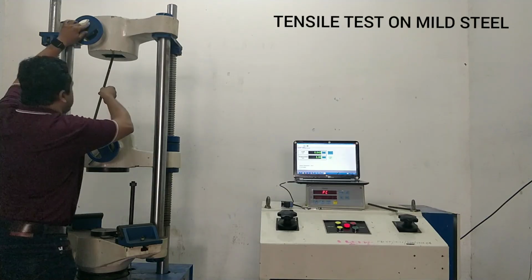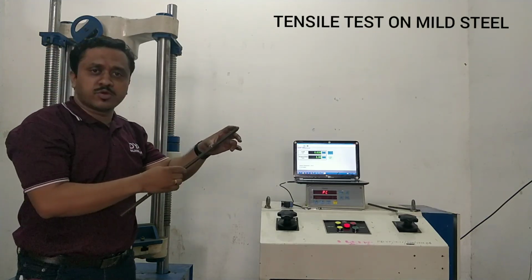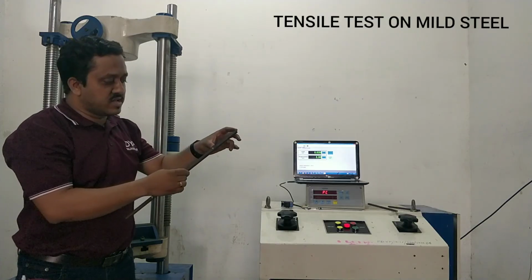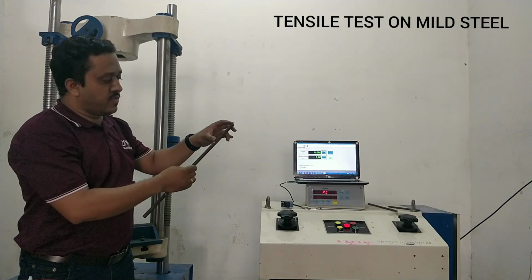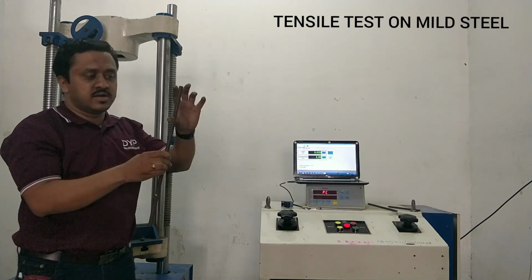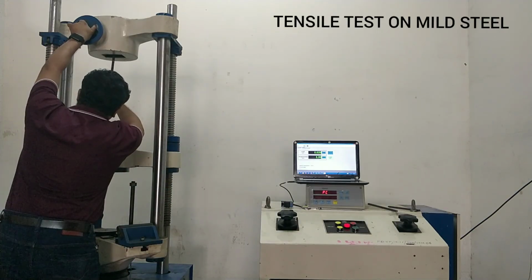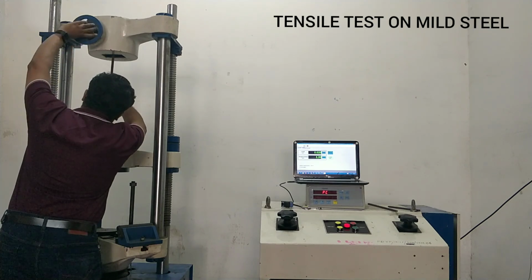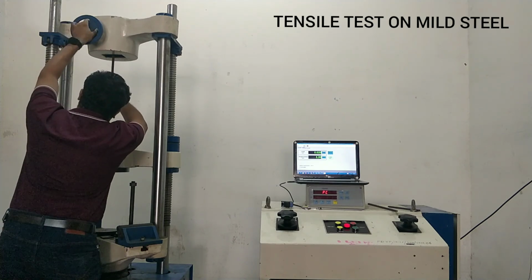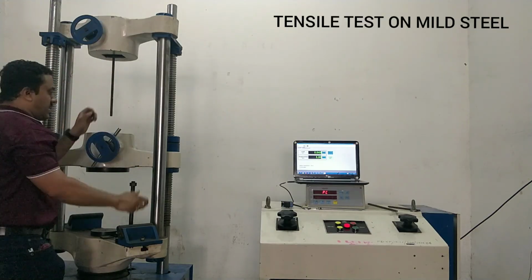First, fix it in the top portion. We have marked the gauge length, which is 5 times the diameter. The gripping length here is around 10 centimeters from both sides, so that the bar has that much grip for the load application. Fix the bar in the upper portion firmly.